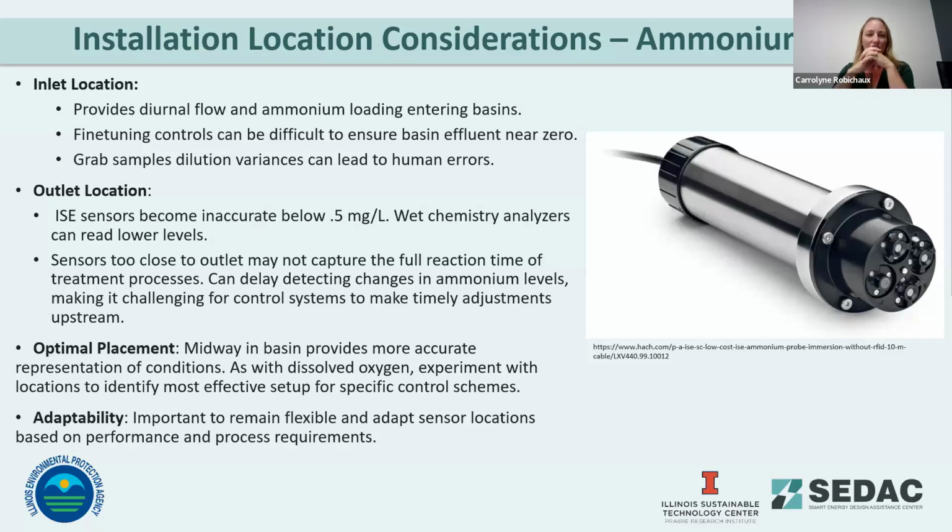Sorry. Your blowers are going to react and you're going to have more air just because it's averaging those 3 sensors. So as far as the control schematic, you're going to want to say, hey, if I've got 2 within 1.5 and then one that drops out to 0, ignore that third probe. Don't average. I hope that makes sense. It does make, as Sean was mentioning earlier, a little bit trickier controls, but that's the whole idea of energy savings, is it does take a little bit to figure out.